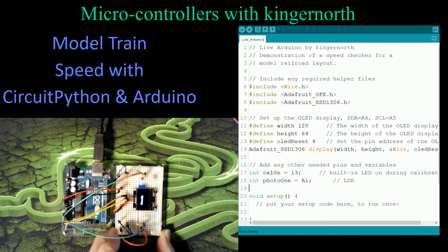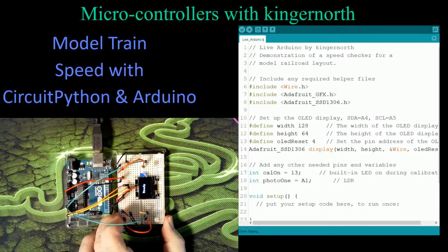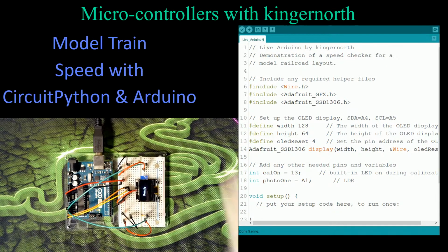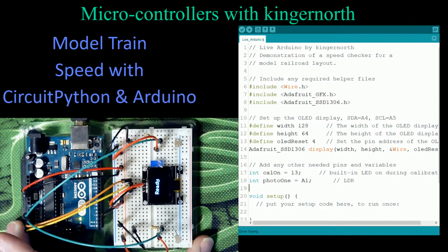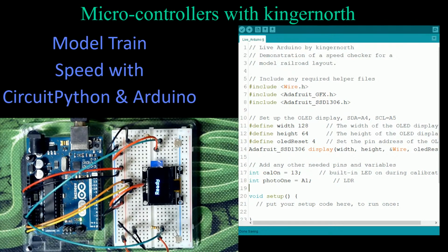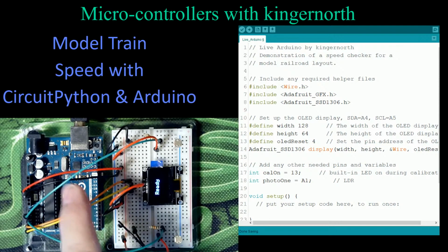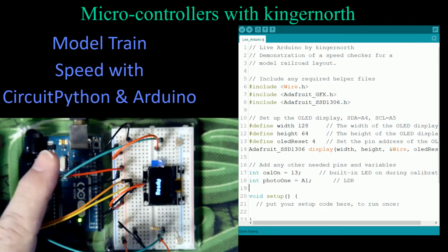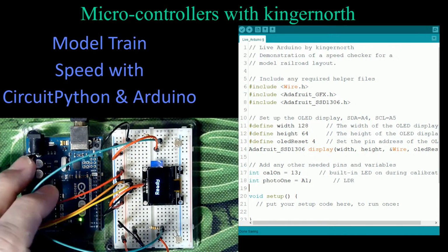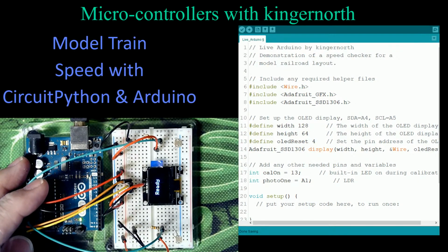So I'm going to turn this, which I know is going to turn the writing in the wrong way. But I'm going to zoom in my camera to get a slightly bigger image of everything that's on here. So this should help make it easier just to see. Up here somewhere, underneath here actually, is the LED light. That's pin 13, and it's hardwired to pin 13, which is just below that black wire. If I move that over a bit, and we get my fingers out of the way so the light can work. This is tricky without me creating too big of a shadow. There's pin 13. There's the LED almost right beside it on this particular board.